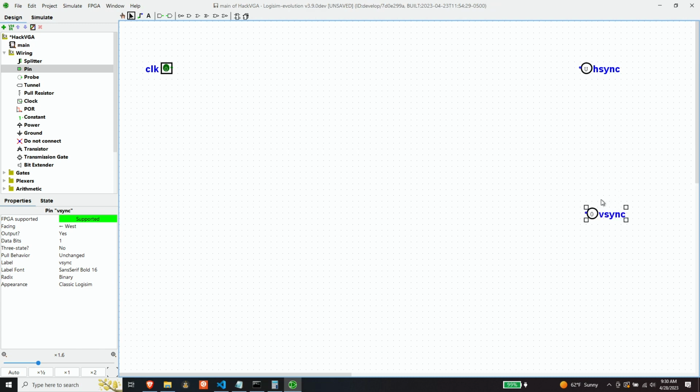Okay, at its most basic, this is what we need, but I want to make this generic. Instead of hard coding the timing values for these two signals in here, I want to feed them into this module to make it more generic. There are actually three sets of parameters that I want to feed in here. The most basic parameter is the total count of pixels for both the horizontal and the vertical. And when I say total count, I mean active and inactive pixels.